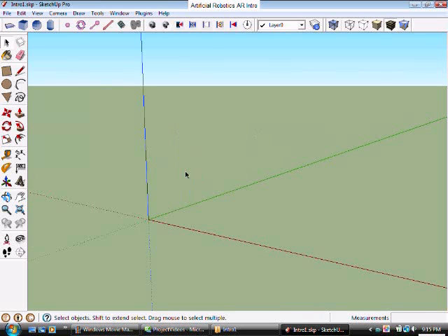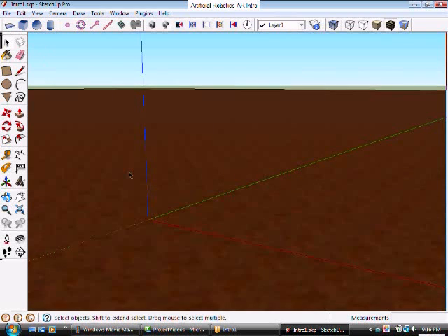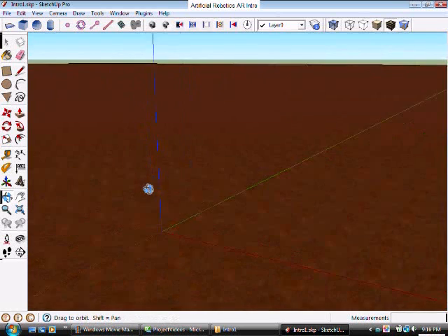What you are looking at is Google SketchUp with an empty work area. Along the top are the tools that you get when you install the AR plugin. Using these tools, you can easily create single shape entities, joints, actuators, and sensors. The first thing we're going to do is click on the ground tool to create the ground. Let's keep the default color and texture.